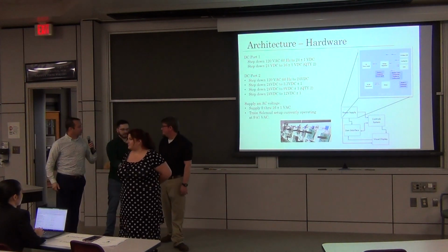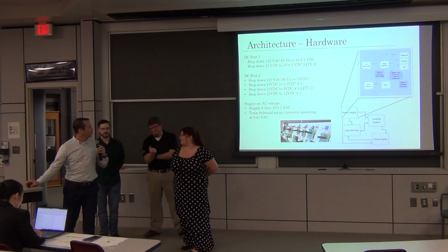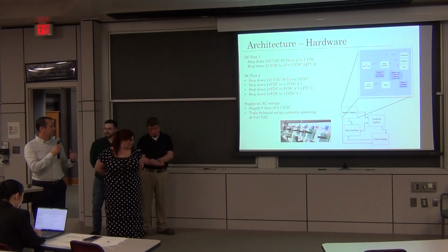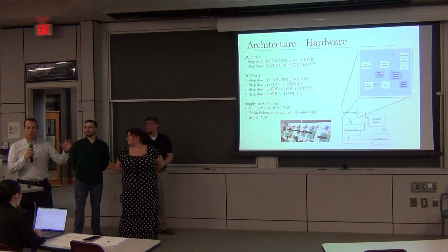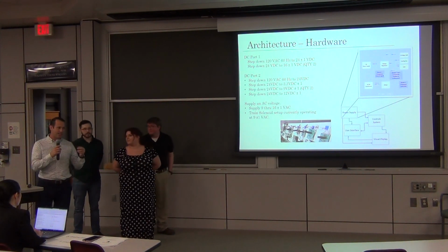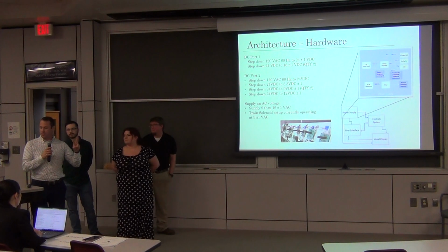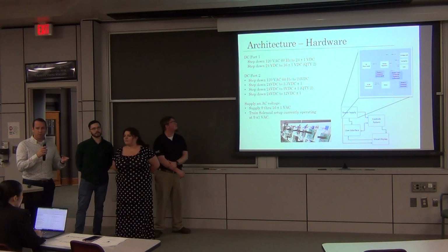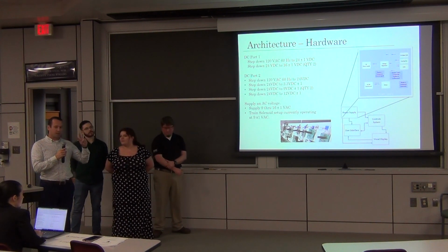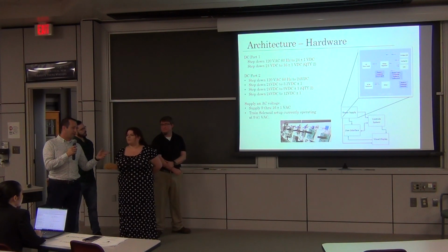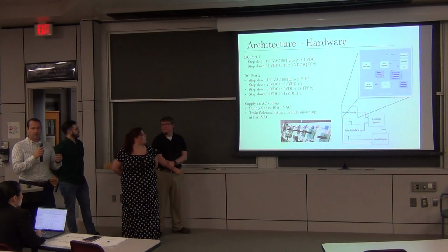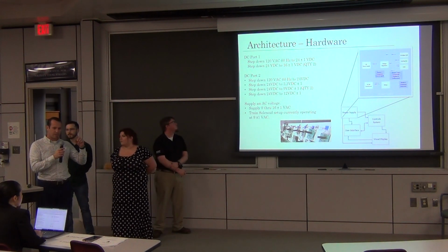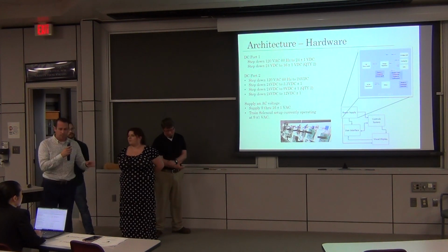All right, so the hardware architecture. In order to power the entire train display, we wanted to have it single plug into the wall, and then we had to step down each of the voltages for each of the sections. James went over all of the modules, but within the modules, we have auxiliary functions that need different voltages. The AC to DC transformer power supply that we have steps it down from 120 volts, 60 hertz to 24 volts plus or minus a volt. That's on 2 ports. Now we divide those 2 ports up into port A and port B. Port A is going to be for the trains. So all the power consumed by the locomotive trains going around the track is coming off of that single port. Everything else is going to be off port B.